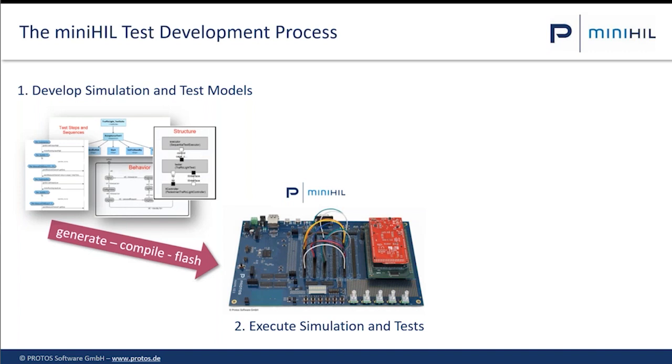So a Python script on your laptop does not work with 20, 30, 40, 50 kilohertz, but a motor simulation or a test for a motor simulation needs to run very, very fast. Sometimes even in the megahertz range. So that's very important, and that's why we use this very specialized hardware and software setup here.